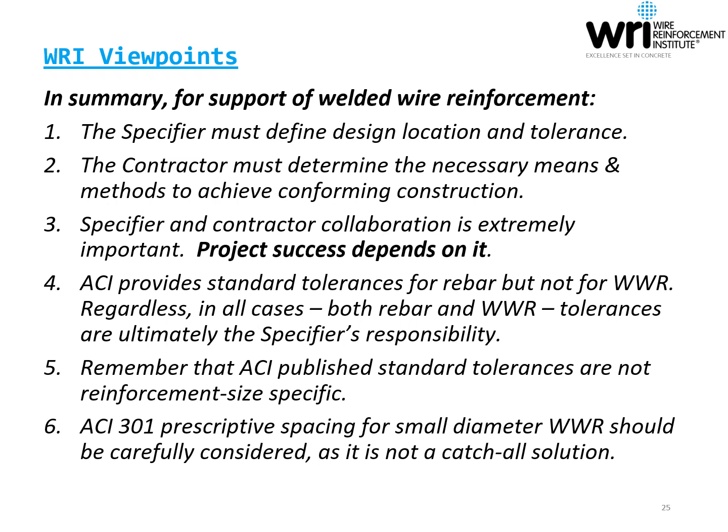ACI provides standard tolerances for rebar, but not for welded wire reinforcement. Regardless, in all cases, both rebar and welded wire reinforcement, tolerances are ultimately the specifier's responsibility. Remember that ACI published standard tolerances are not reinforcement size specific. And lastly, ACI 301 prescriptive spacing for small diameter welded wire reinforcement should be carefully considered, as it is not a catch-all solution.